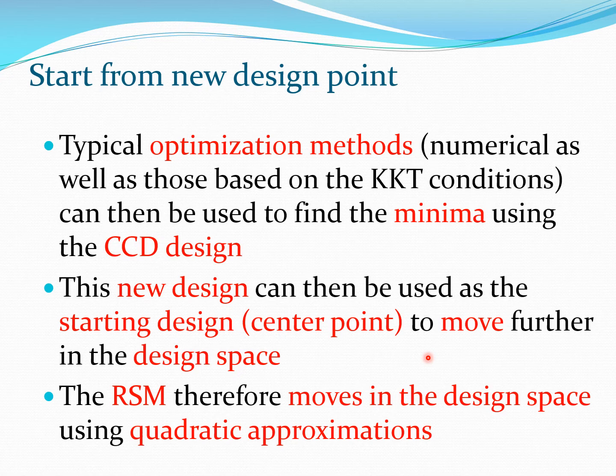So this is very important, that the new design, which may actually lie on the boundary of the feasible region of the first design, is then taken as the center point, and then you again take a perturbation around this center point of plus minus 15%, and you move further in the design space in this manner, while restricting each move to within the region of validity of the response surface, which you determine by your perturbation in the high-low system.